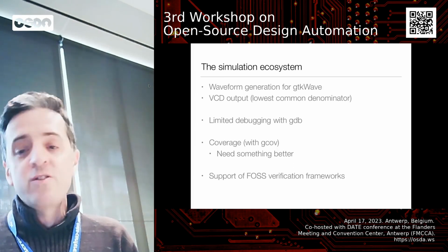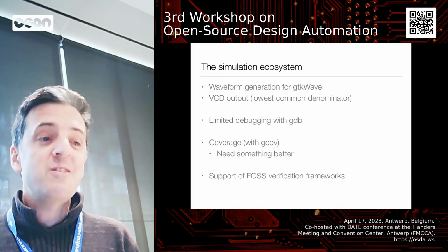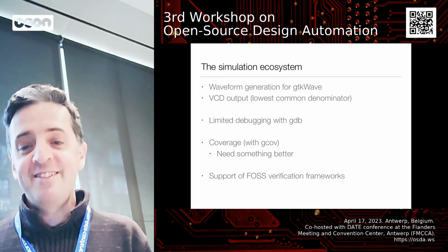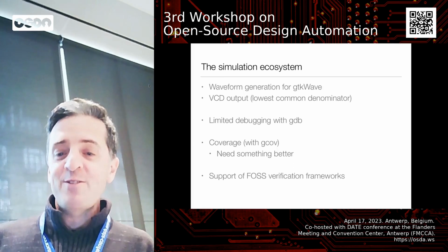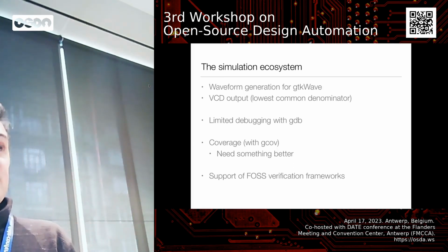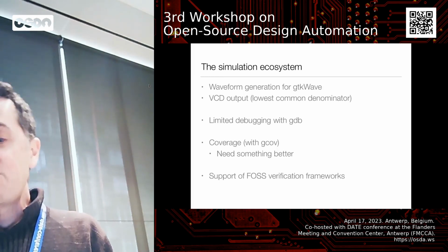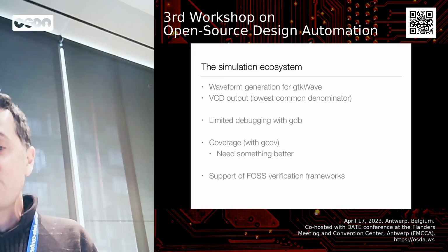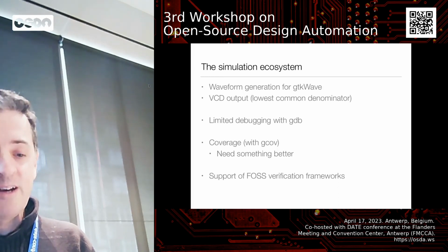Because it generates code, you can do some debugging of your model using GDB, but it's not completely nice. Because it can use GCC as a backend, you can do some coverage with gcov. That's also something to be improved. And it supports most of the open source verification frameworks, like UVM or OSVVM.